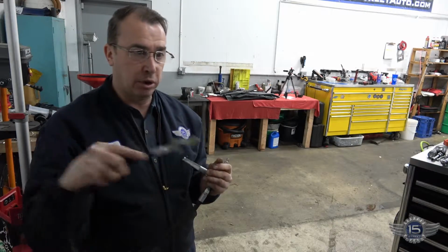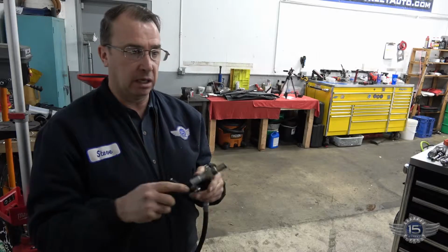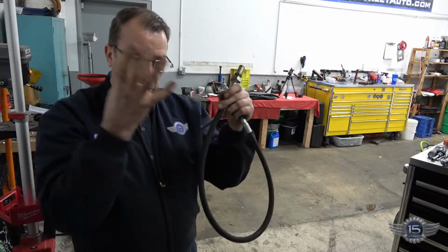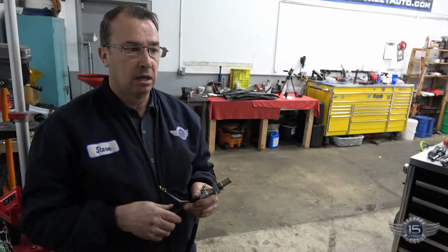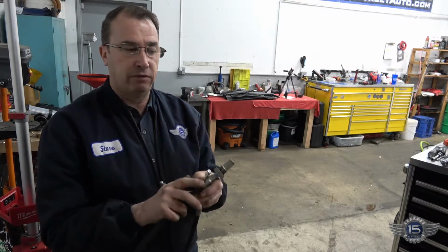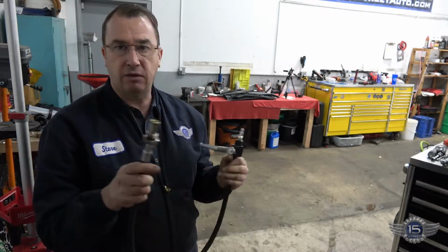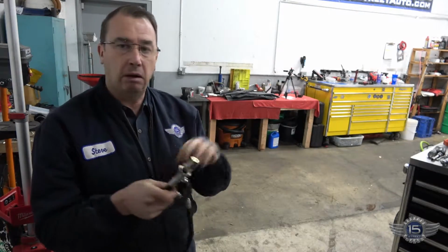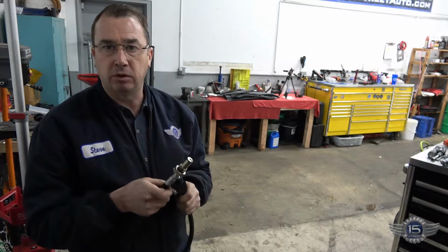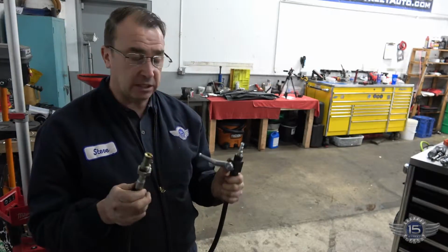So what I do is I'll put it in there, I'll put air to this thing, and let it sit for 10 minutes while it pushes out any oil in the channels. If there's no air leaks, then I will close this valve off, unhook my hose, and let it sit there for 10 minutes. When I open this valve, if there's still pressure on it, I know there's not a leak in the system. All that pressure would have bled off by then. So that's a good test for that.